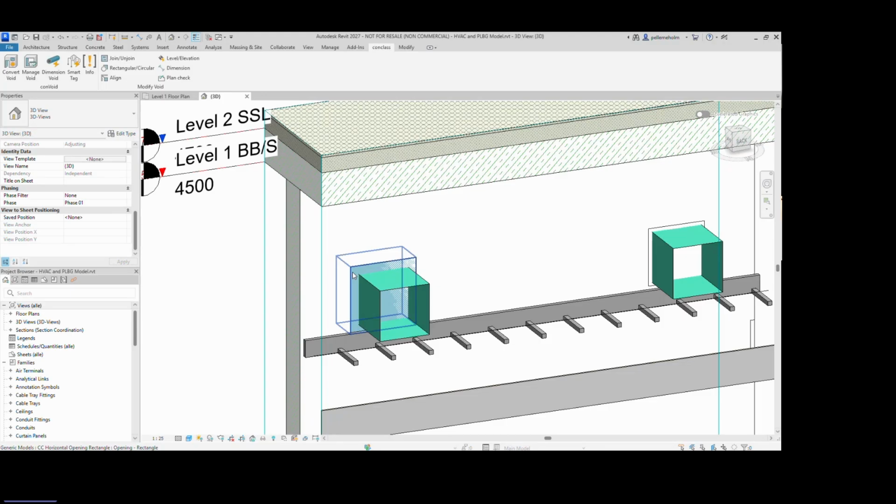And even if there's no real clash, the construction site needs to seal all the openings which are required for fire safety. And they need specific spaces or clearance to fill this opening. And in case there's not enough spacing, the sealing mass will not fully cover the entire opening.